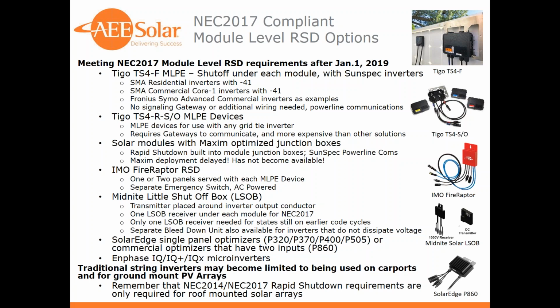Also available for use with just about any grid-tied inverter is the Tigo TS4-R-S or the -O MLPE devices. The S is for safety, and the O provides the safety features and also additionally optimization functions there. Just like the Tigo F, one would be deployed behind each module.